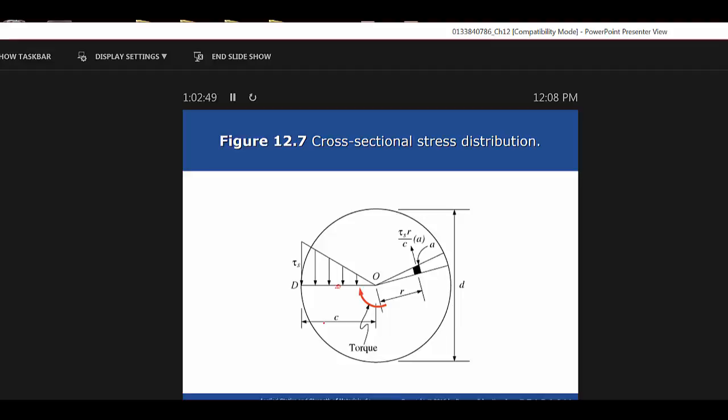So for the hollow shaft now, it's a little bit different. Note, and some people did this on the temperature thing, you tried to do like 0.030 over each one of those temperatures, and that wasn't quite right. You couldn't do that. Same thing on this. If you want to find the polar moment of inertia, note that they're taking each one of the diameters and raising them to the fourth power.